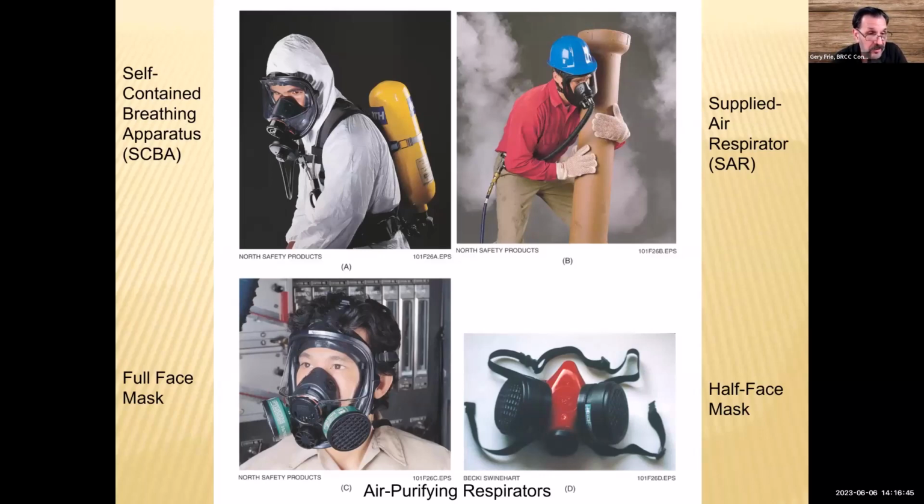But if there's not enough oxygen, then that's not going to help. And if you don't have the right kind of filters in there, it's not going to help either. If you have to worry about asbestos or silica or some other sort of dust, then you need the dust filters. But if you've got a paint fume or lacquer thinner or some kind of fume, then you need a different kind of filter that can deal with fumes. That's a much tighter particle size filter.